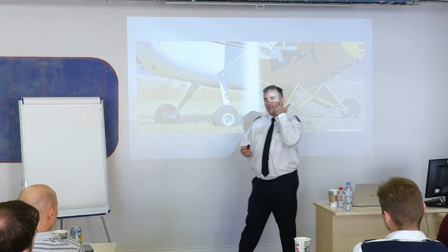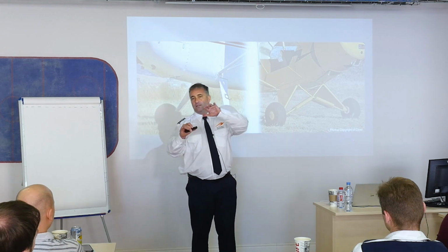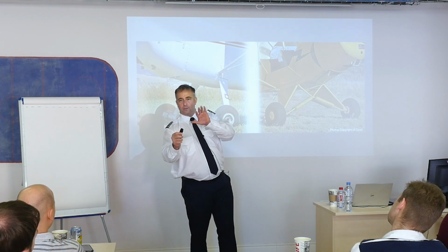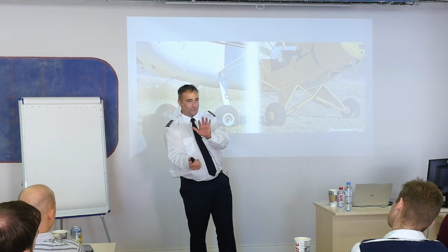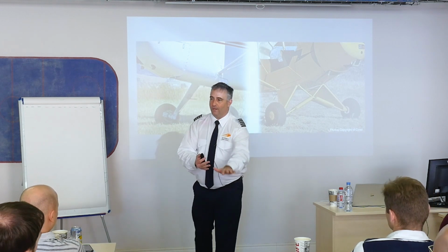Now I start thinking that whichever way the wind is coming from, I probably need to land on that tire first. And the idea is, as the airplane slows down, I use more and more aileron, and then gravity slowly brings the downwind tire to earth. And then I gradually release and bring the nose wheel down.